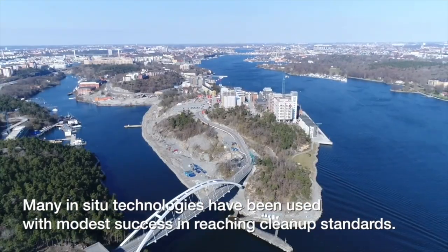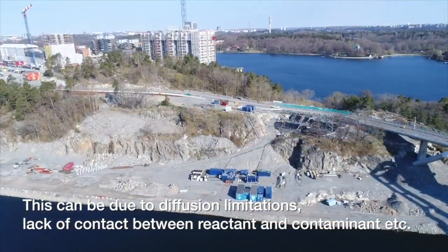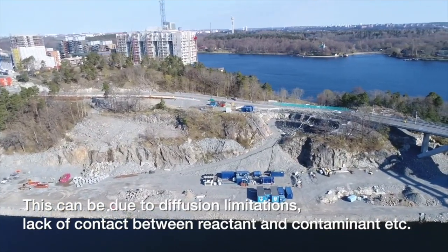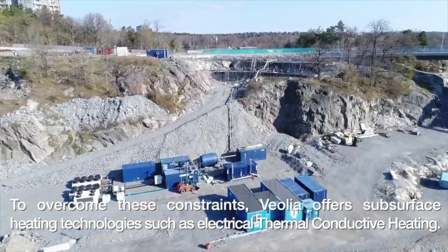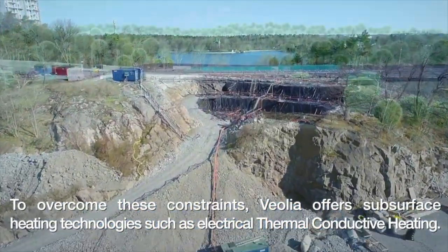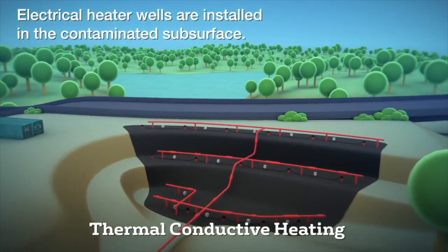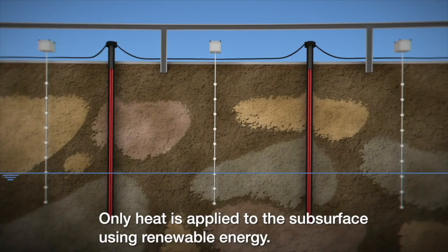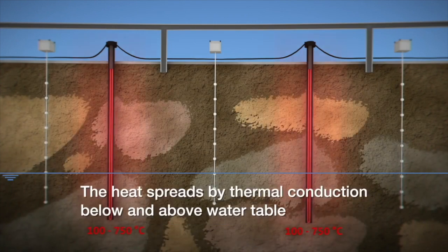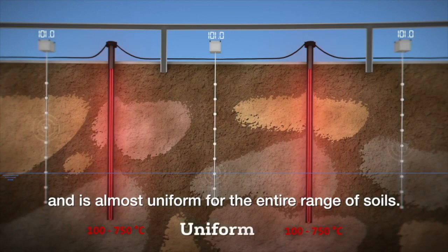Many in situ technologies have been used with modest success in reaching cleanup standards. This can be due to diffusion limitations, lack of contact between reactant and contaminant, etc. To overcome these constraints, Veolia offers subsurface heating technologies such as electrical thermal conductive heating. Electrical heater wells are installed in the contaminated subsurface. Only heat is applied to the subsurface using renewable energy. The heat spreads by thermal conduction below and above water table and is almost uniform for the entire range of soils.